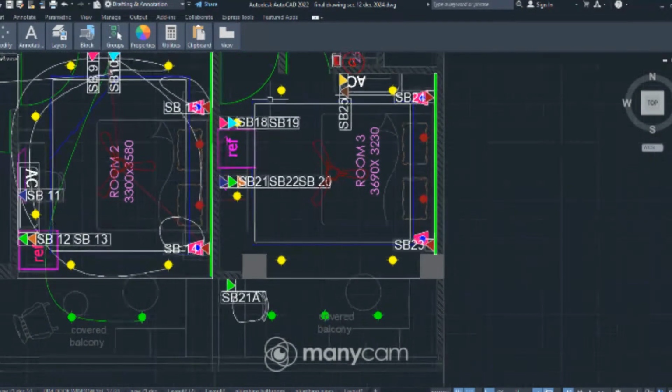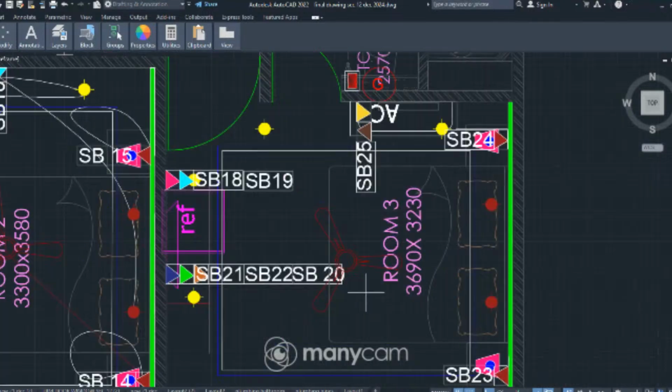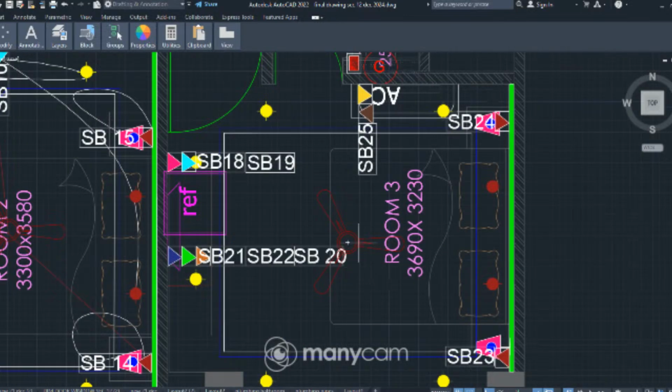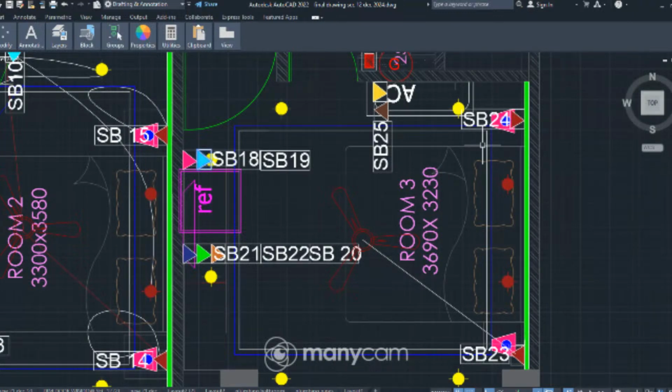Now for electrical looping, I've given you the fair background of what exactly we have given. So here, this is a small boutique hotel, so we will not be giving a lot of two-way switches. Else, generally side tables also have two-way switches for all your lighting. Here we are just giving a two-way switch for your fan because this person will be a little far from the main switchboard, and this main switchboard is almost here to the person staying who will be sleeping on this side.